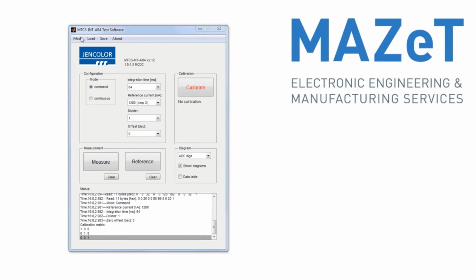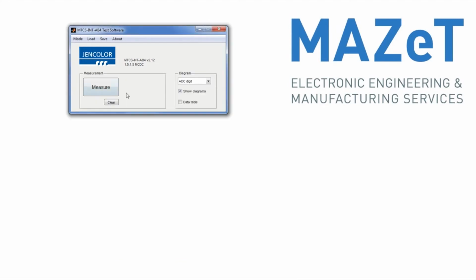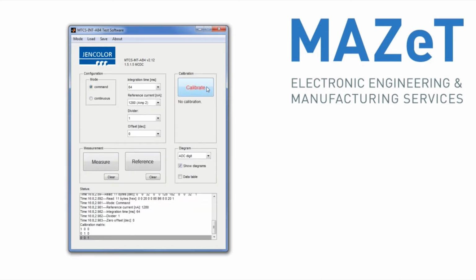The software of the MTCS-INT-AB4 allows various options for calibrating an application. There are the Expert and Easy mode. The calibration takes place in the Expert mode. You can choose between Command mode, Measure at Click, and Continuous mode. Depending on the application, you need to set up adequate integration time, reference current, divider, and offset settings. Please check the datasheet for further information and recommendations.